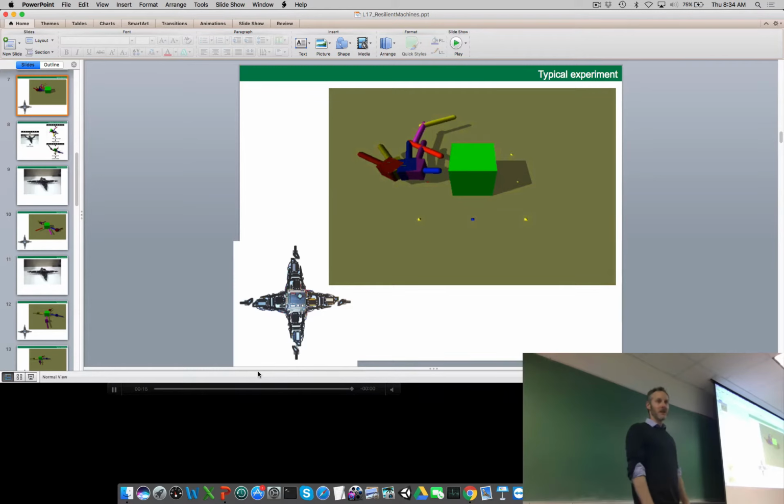By the degree of the base? The degree of the base. Remember that the physical robot and the simulated robot have these 2 vestibular sensors: how much the main body tilts left and right, and how much the main body tilts forward and back. How do we use that vestibular sensation to measure the accuracy? You get a value with the real world one, and then you try to get that same exact value with the simulated one. Exactly. So we have physical sensor data. We actuate the virtual robot, which generates virtual sensor data, and then look at the difference between these 2 sets of sensor data. The closer they are, the more accurate that simulator must be, right?